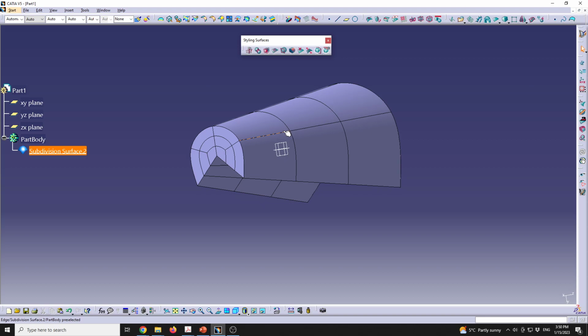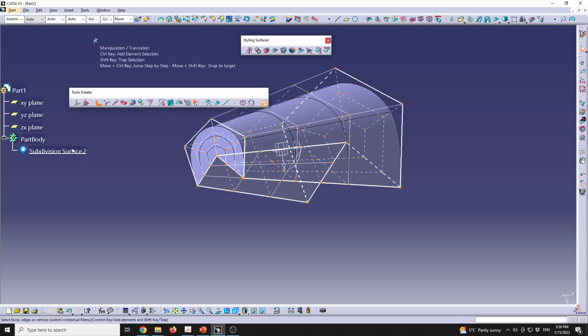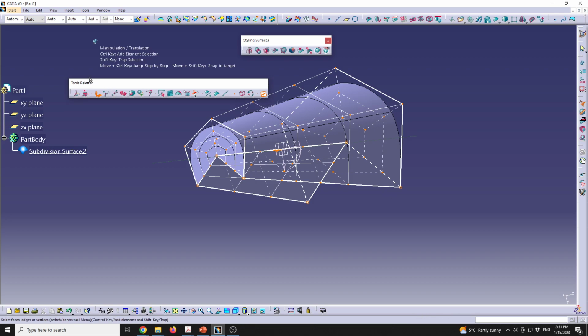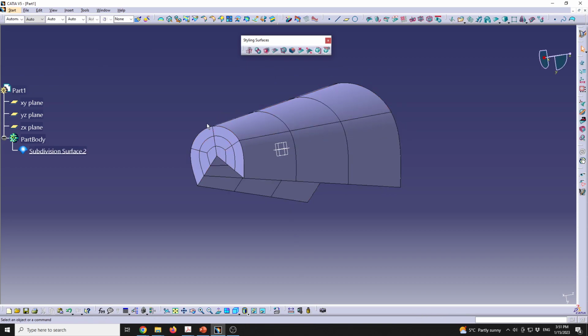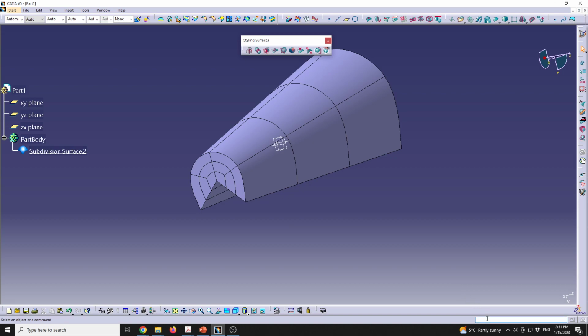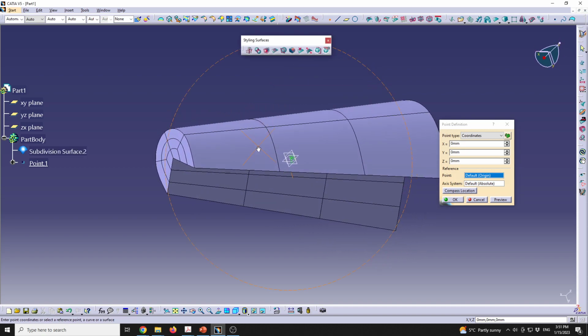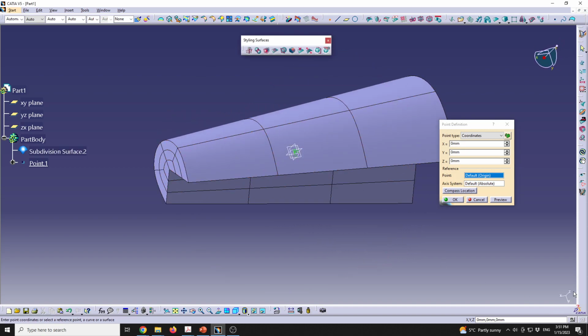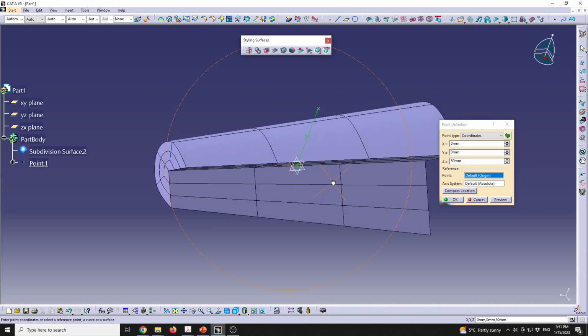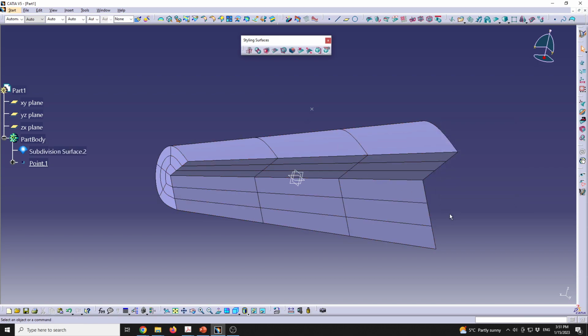Also keep in mind that once an advanced primitive has been defined, you can no longer edit that. So for this, if I go to edit, I'm going to go to the standard tool palette. So I no longer have access to all that information. But now if I create a new point, I have the possibility to add some coordinates for this point. So I'm going to go on the z-axis with 50. So this will be my new point.